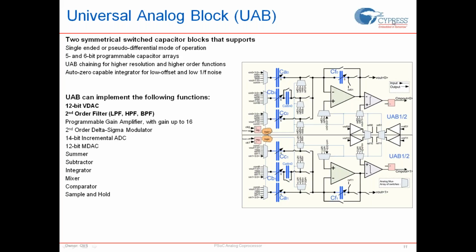And all of these are implemented with resistors, which are RAM-based resistors. That means you can have code that updates them dynamically too. So yes, you can program them, and you can also program them on the fly if you can figure out what those registers are.